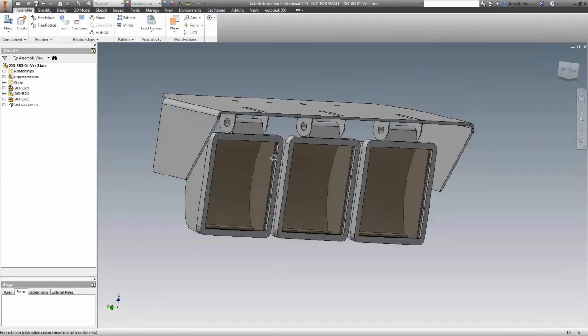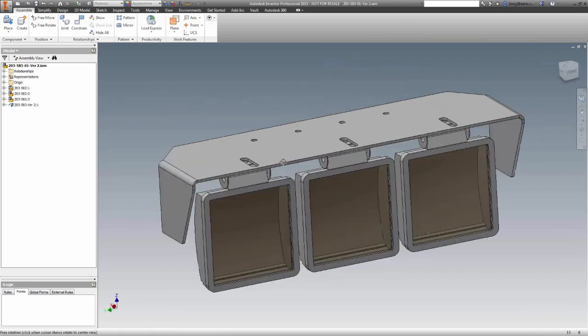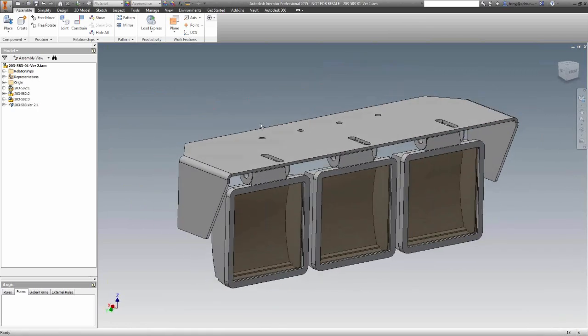Now what you'll find is while you're working with Inventor or with any of the CAD packages, as I said earlier, it will start asking you questions about how it makes changes to the files. So do you need to check a file out? Do you need to check it in? Do you need to get the latest of that file?